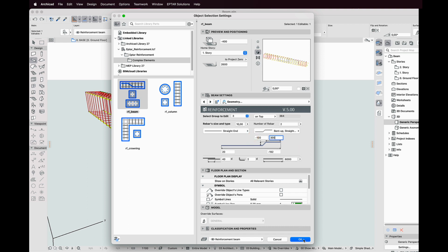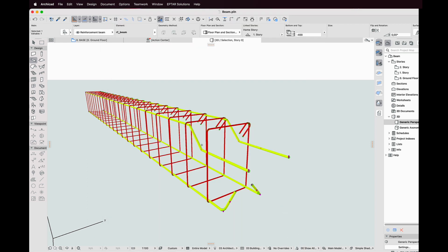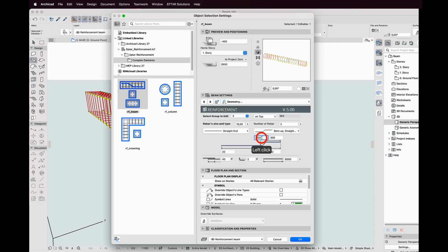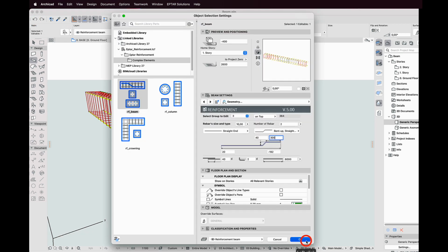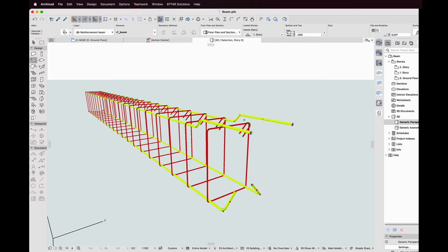The direction is almost good, but the bend size is too big. I set a little bit smaller value for it. Now it's better, but this was the old method to set a good direction. I click on Undo again. I set the values without a minus prefix, then click on OK. In the 3D window, I can find some purple hotspots for modification on this rebar group.